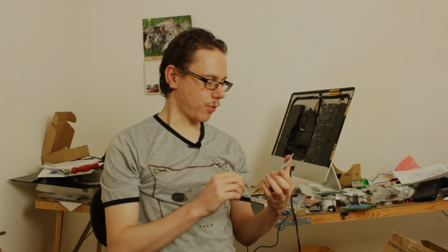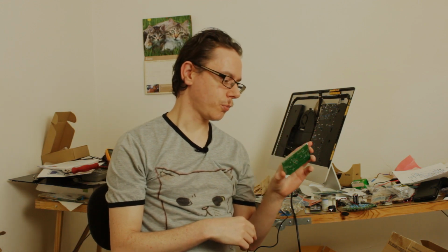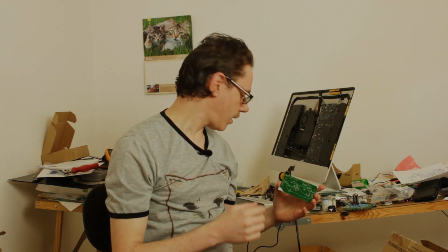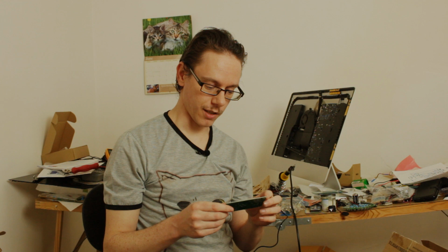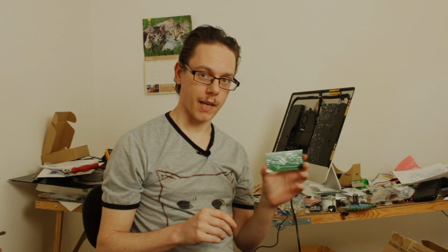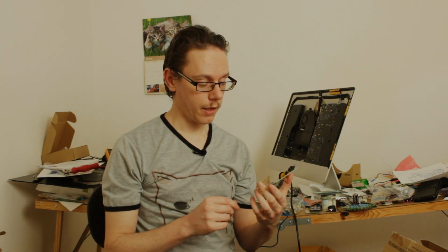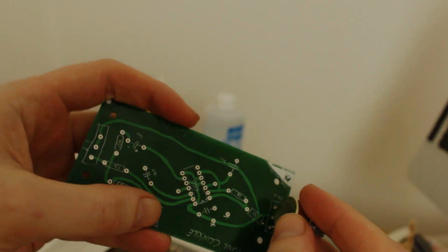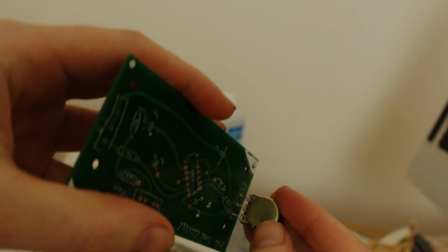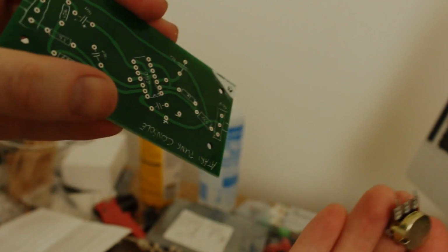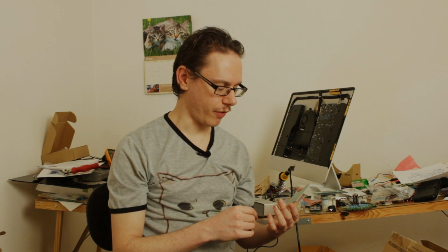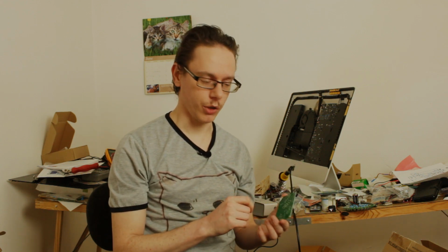And here's a little bit of a problem. When I made this, the holes that I put in are 0.8 millimeters. Well, the problem with that is that the pots and actually the audio jack need bigger holes, so this doesn't fit. Now the pots you could technically just wire in, but it's going to be a little bit difficult to do, the same thing with the audio jack.